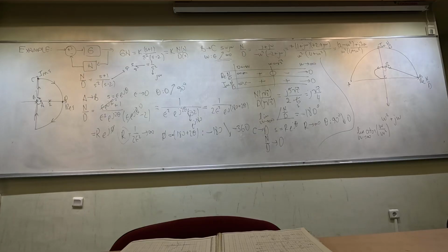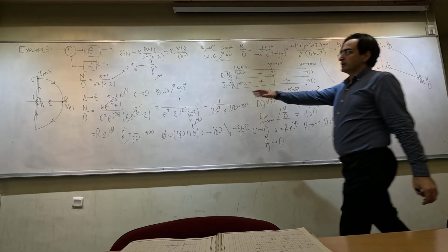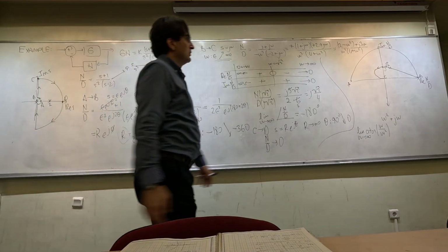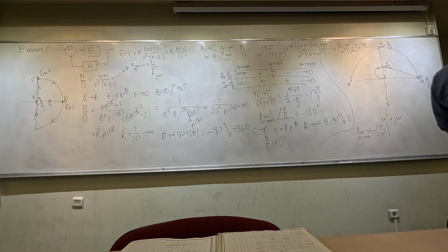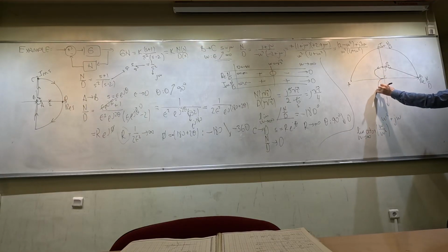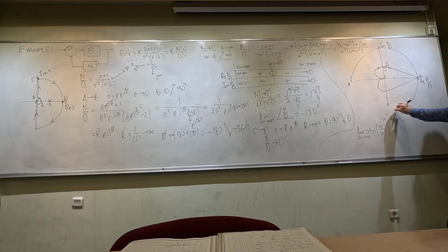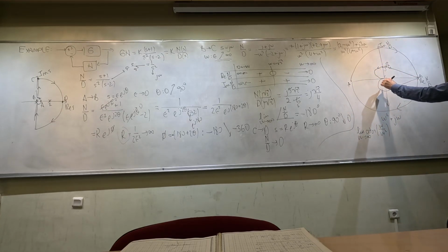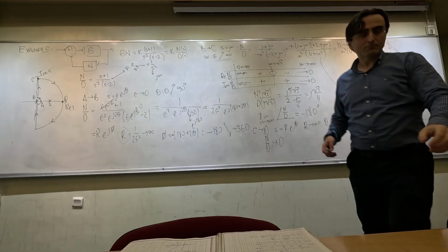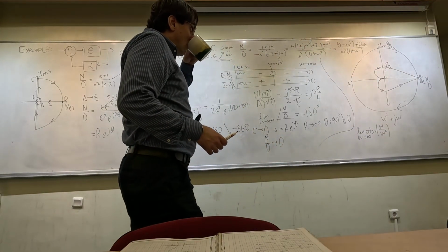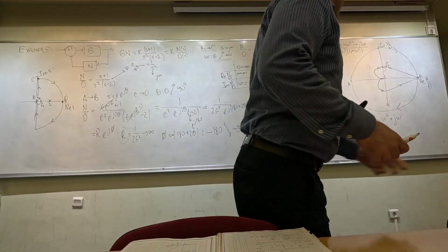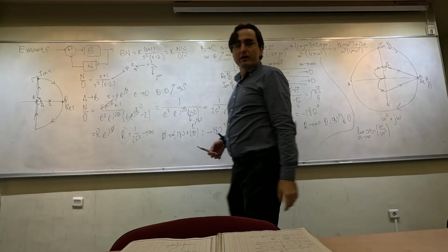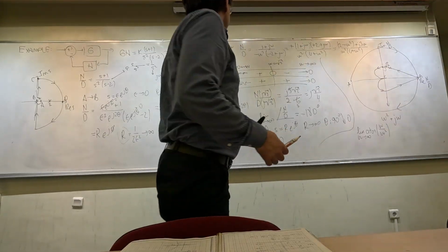So now I'm going to complete the other half. We are considering real coefficient polynomials, meaning that the other half is just the complex conjugate symmetry of this part. So I'm continuing to draw the plot here. I will draw something like this, and I will complete this to the full scale. So now this is our Nyquist plot, and what I would like to do is to make a stability analysis based on that plot.